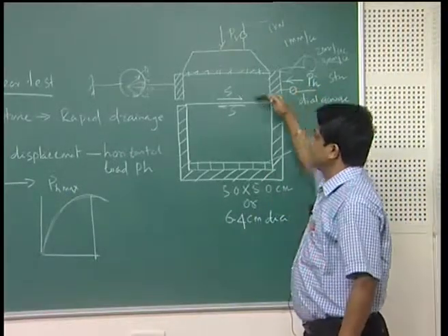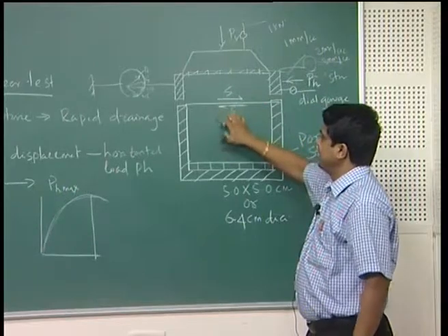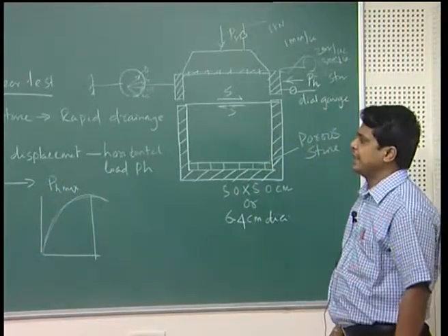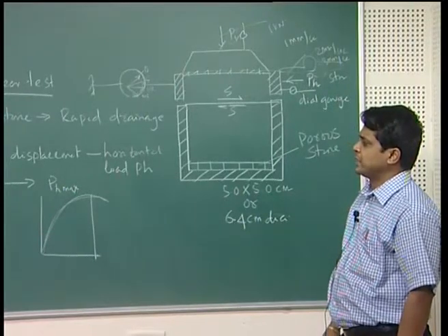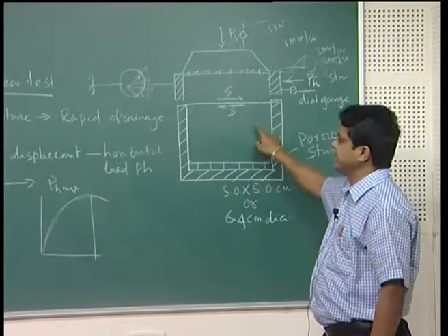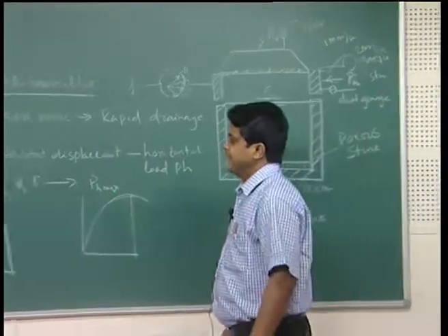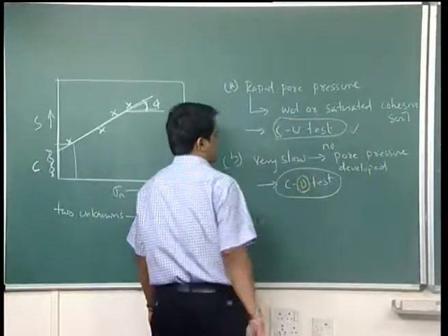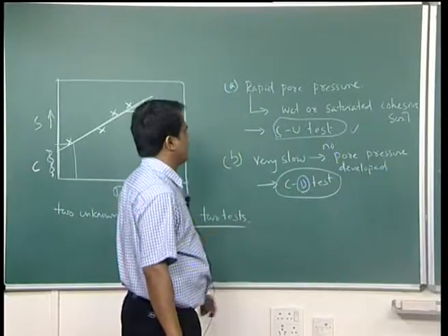It is so slow, so what will happen? The development of pore water pressure will be very little, or there will be no pore pressure development. So, that will simulate the consolidated drained test. That means the drainage will be there, so no pore water pressure will develop.